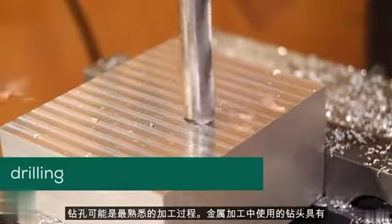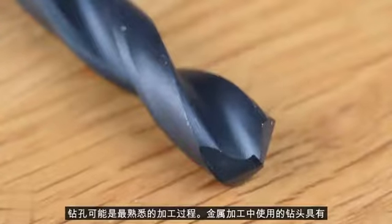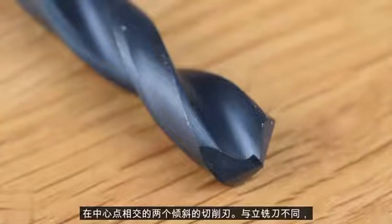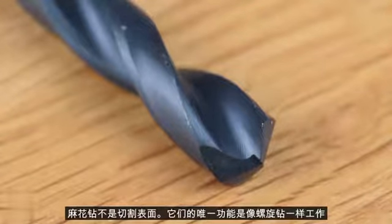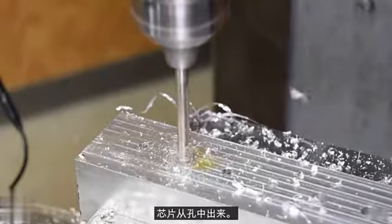Drilling is probably the most familiar machining process. Drill bits used in metalworking have two angled cutting edges that meet at a center point. Unlike an end mill, the flutes of a twist drill are not cutting surfaces. Their sole function is to work like an auger, conveying the chips up and out of the hole.